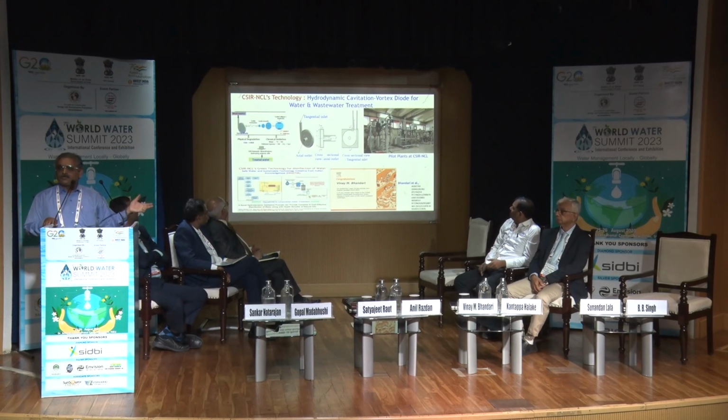Okay, this device is also available commercially now. There is a startup based on this development, they are selling the device. So this is the vortex-based cavitation. We generate a vortex such that there is a sudden pressure drop at the point, and at that point, part of the liquid flashes into vapor, and then bubbles are generated.